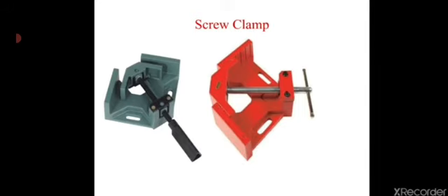The limitations of these screw clamps are that the clamping force is not the same for all components. Relatively larger effort is needed for clamping. The time taken for this clamping is more, and if there is no floating pad, an indentation may be produced on the workpiece.